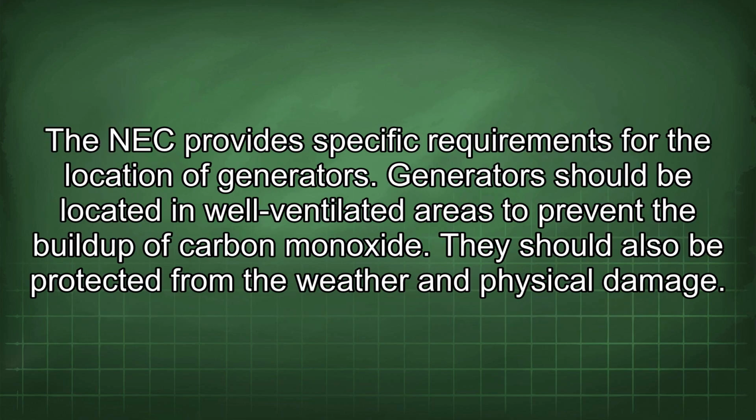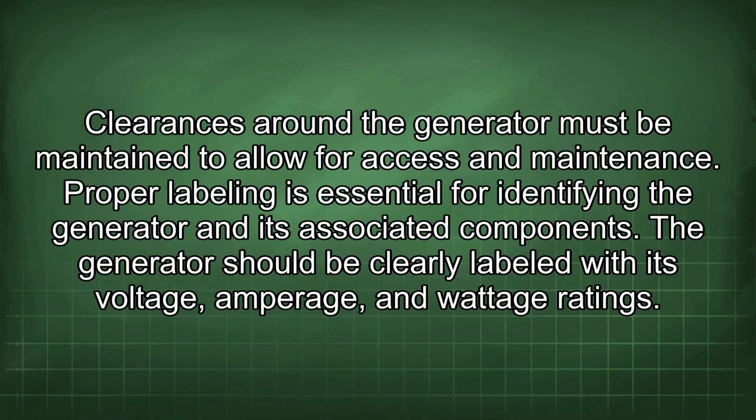The NEC provides specific requirements for the location of generators. Generators should be located in well-ventilated areas to prevent the buildup of carbon monoxide. They should also be protected from the weather and physical damage. Clearances around the generator must be maintained to allow for access and maintenance.